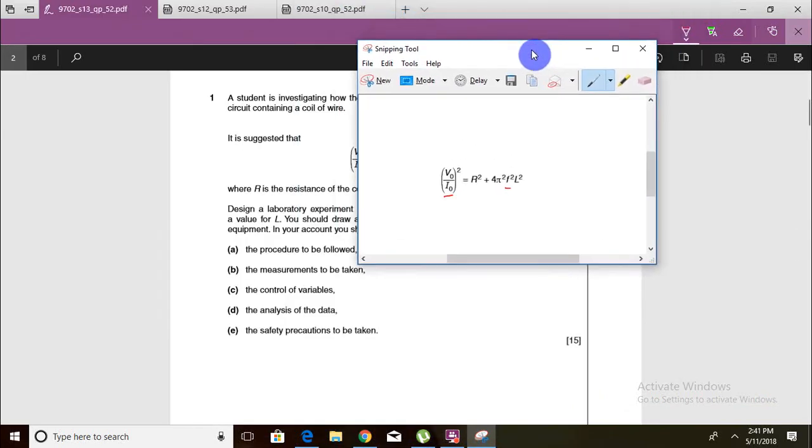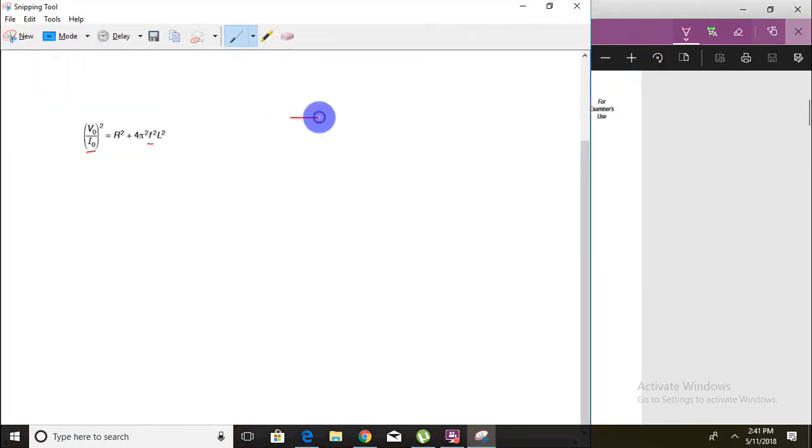So how do we do that? Well, we can have either a signal generator or a variable frequency AC power supply. Both of these can work. In this case, this is the symbol of a signal generator, right? So we can use that. In my opinion, that is our best bet. So we have managed to figure out a way in which we can vary the frequency while keeping V0 constant.